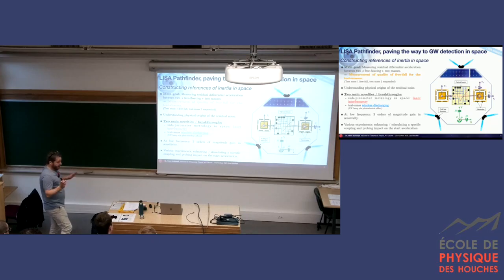With the Pathfinder, we did not do that. So the concept was we're going to use the photoelectric effect. We're going to illuminate the test mass with UV, and we're going to pull the electrons off without any mechanical contact. So it was new. I think it was a kind of risk, a novelty, but it worked beautifully. And it gained us 2 orders of magnitude at low frequency in acceleration noise. That was a big step. Now, all the metrology missions are interested in using that new method.